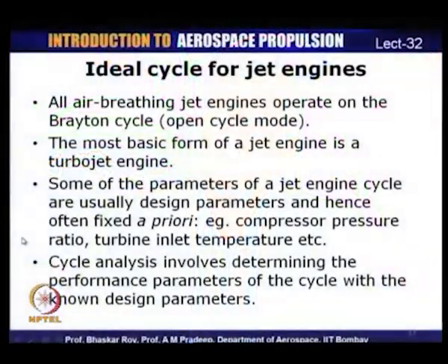All jet engines, all air breathing engines, basically operate on the open cycle mode of the Brayton cycle, and the basic form of a jet engine we can consider is a turbojet engine. In a turbojet engine, some of the parameters which we shall come across are so-called design parameters and are often fixed a priori, like the compressor pressure ratio or the turbine inlet temperature ratio.